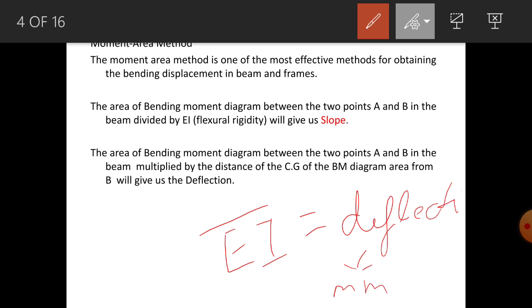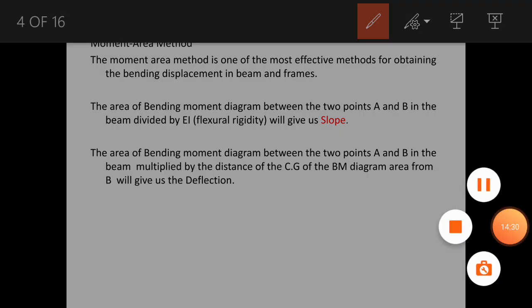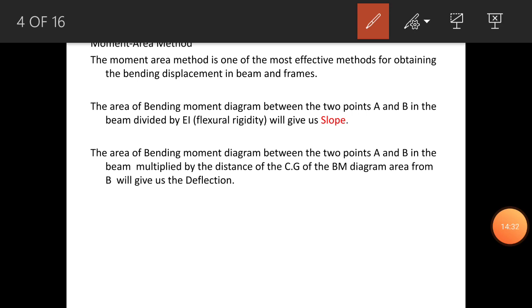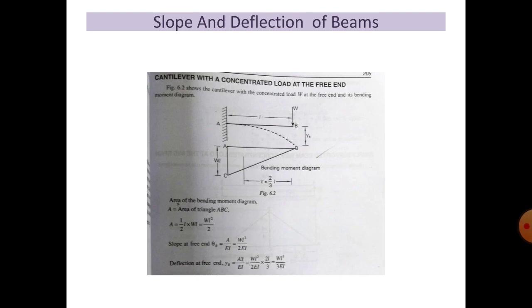So if you want the deflection in mm, your load should be in Newton, and your length should be in mm. Okay, that is very important. Your dimension units are very much important.